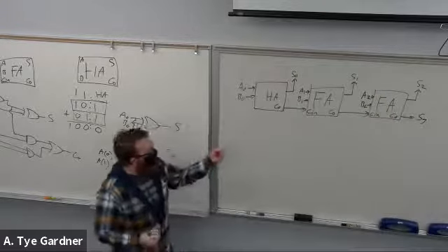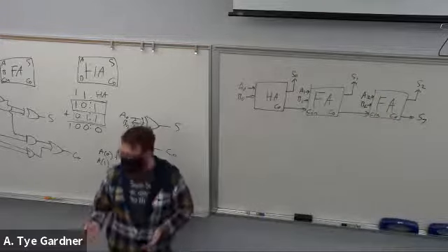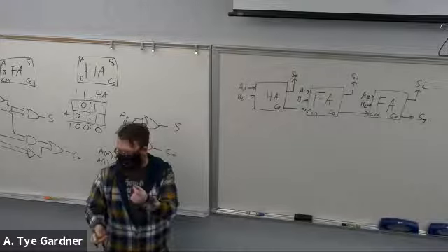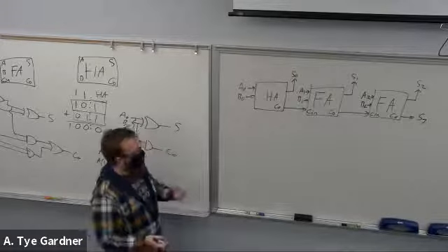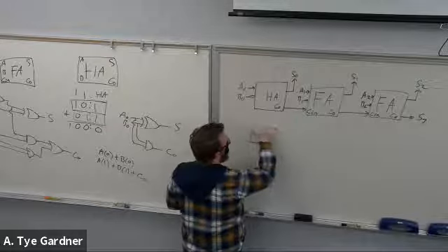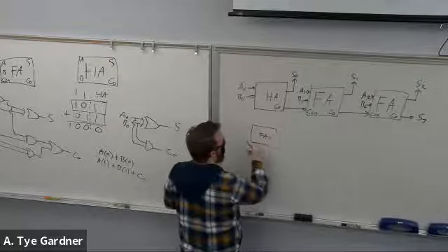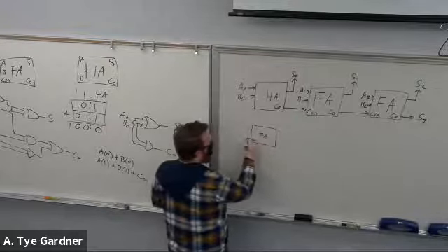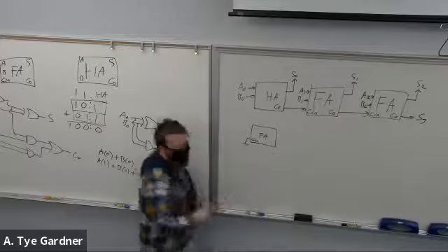So this half adder, if all I had was full adders, say I had little integrated circuits, right, the little black chips of full adders, and I had no half adders, a half adder is equivalent to using a full adder where I take the carry in and just tie it to ground or 0.